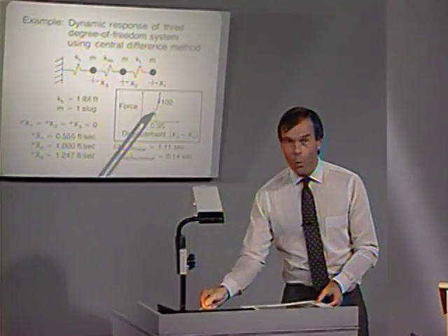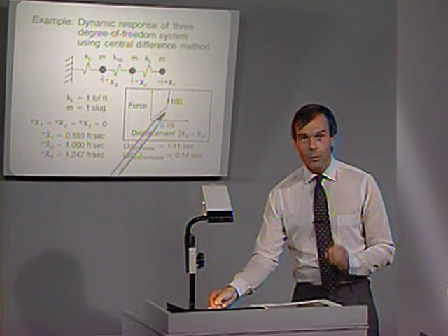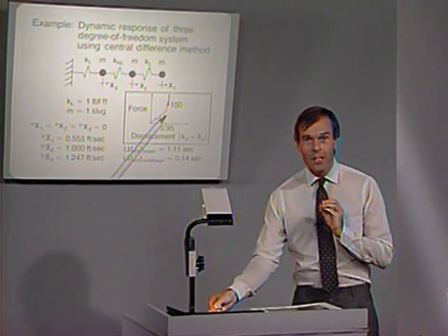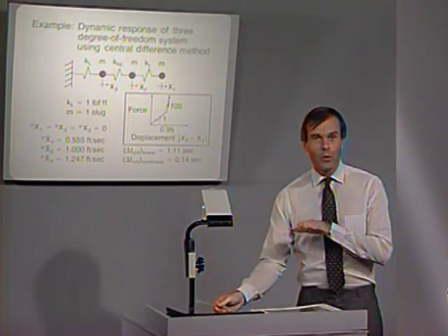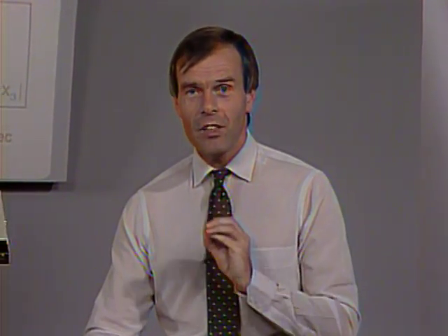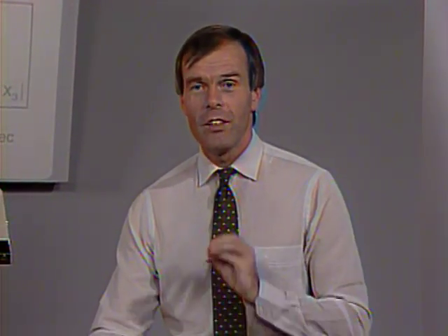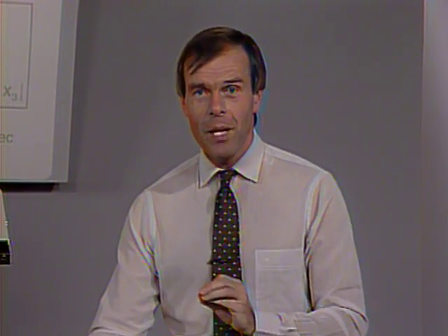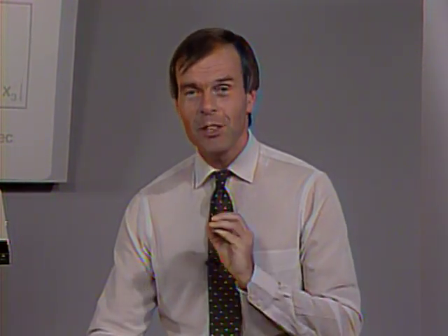That error which you have accumulated, of course, is carried forward, but you have not seen a blow-up of the solution. And that's one important consideration when you apply the central difference method in nonlinear analysis. Of course, the important point, the ground rule that you have to observe, is that delta t must always be smaller than the critical time step of the mesh, where that critical time step changes throughout the solution.